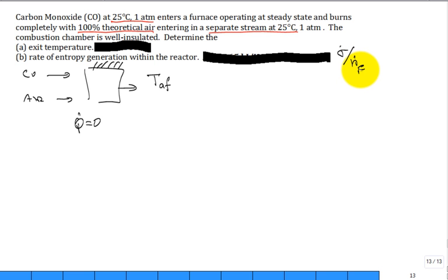All right. So how do I calculate the exit temperature? Get a balanced reaction equation for the carbon monoxide. Here's my O2 plus 3.76 N2. Okay, it produces carbon dioxide, CO2, one of them. How much water does it produce? H2O. I'm so used to burning a hydrocarbon that I want to put water in the products. But is there any hydrogen? No, there's no hydrogen in the fuel. No need for it. Okay, how about the N2? Sure, we're going to need that.